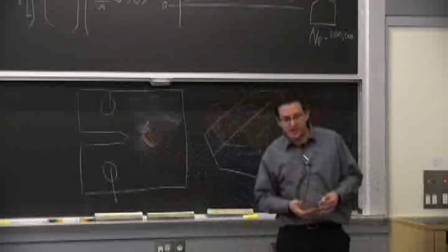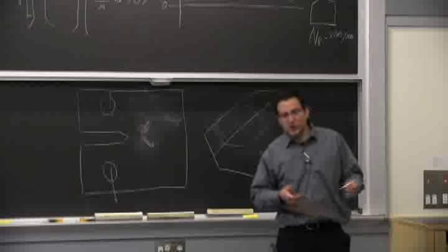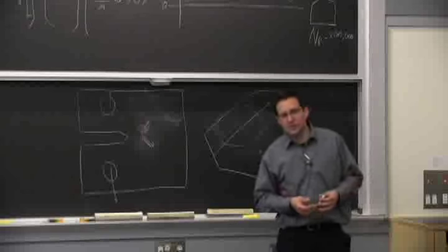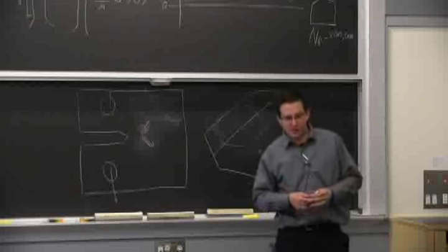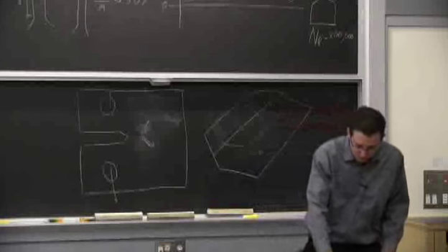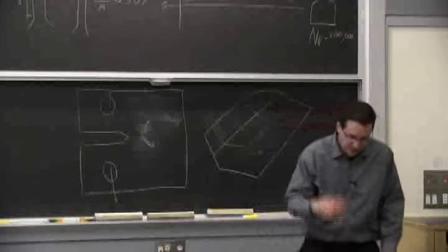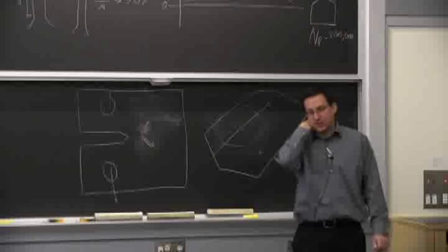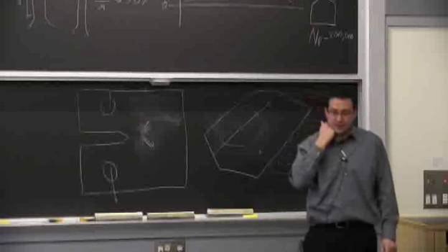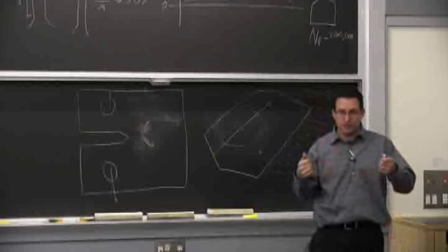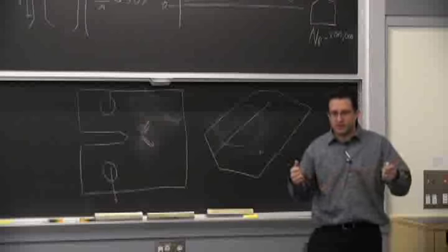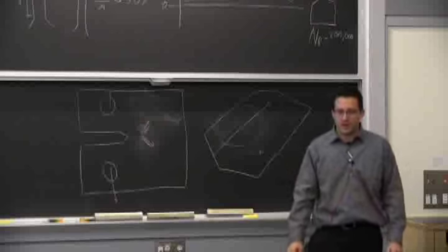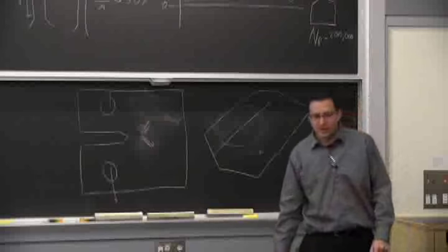So from an assessment standpoint, we don't need to go and look at striations, the same way that for fracture toughness, we don't go look at the plastic zone size. I'm really trying to introduce you to it in detail so you have an understanding of why it is, for example, that the cyclic load will really grow a crack. And the answer really is by blunting it and resharpening it, blunting it, resharpening it. Ceramics are a little bit the same way.